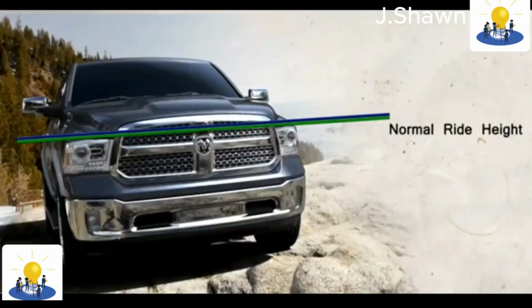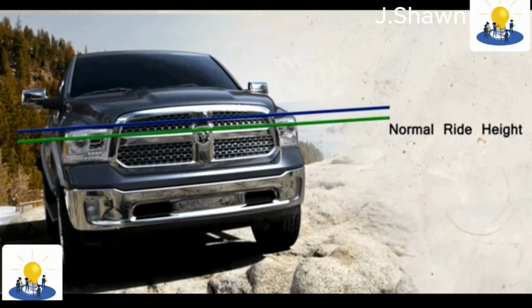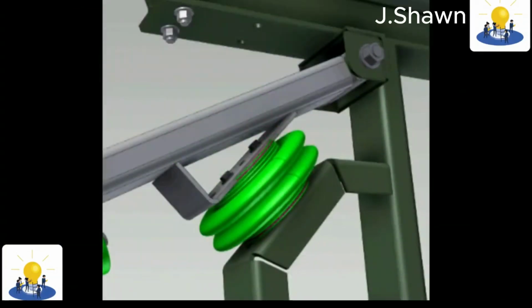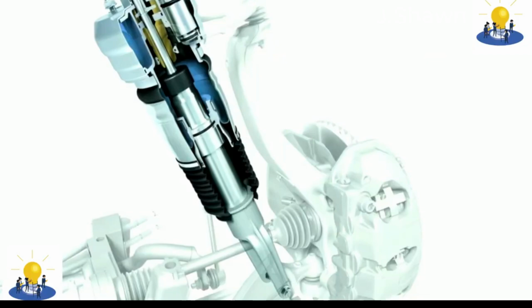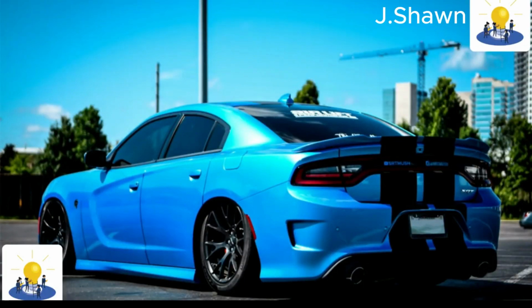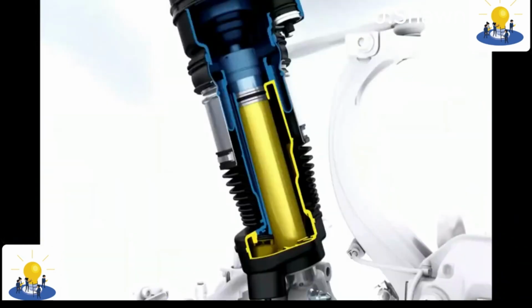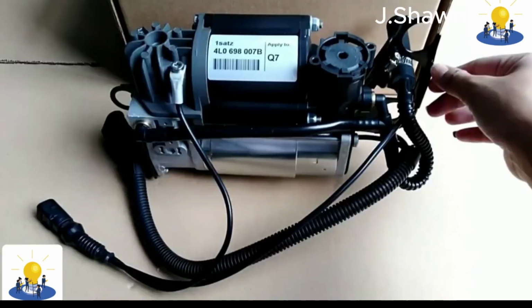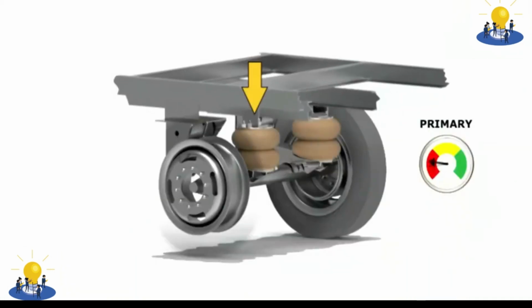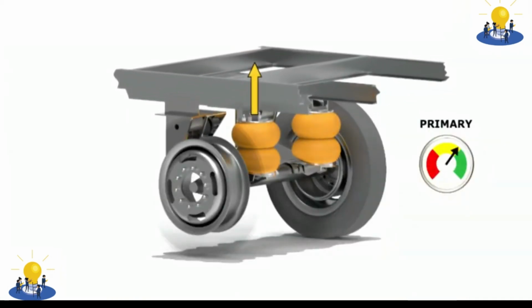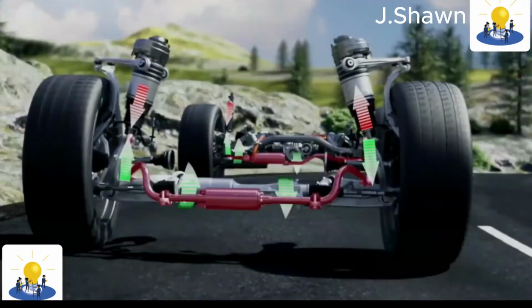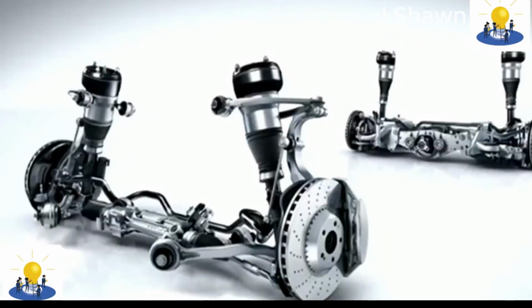Air suspension is used in place of conventional steel springs in heavy vehicle applications, such as buses and trucks, and in some passenger cars. It is widely used on semi-trailers and trains, primarily passenger trains. The purpose of air suspension is to provide a smooth, constant ride quality, but in some cases it is used for sports suspension. Modern electronically controlled systems in automobiles and light trucks almost always feature self-leveling along with raising and lowering functions. Although traditionally called airbags or air bellows, the correct term is air spring, although these terms are also used to describe just the rubber bellows element with its end plates.